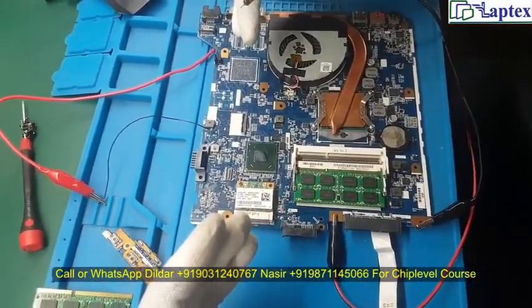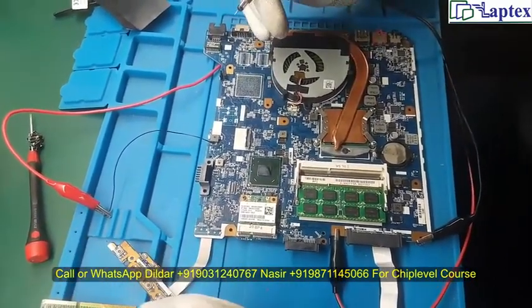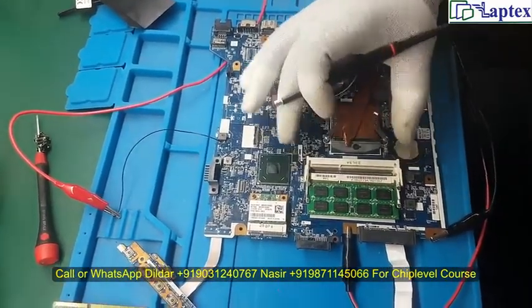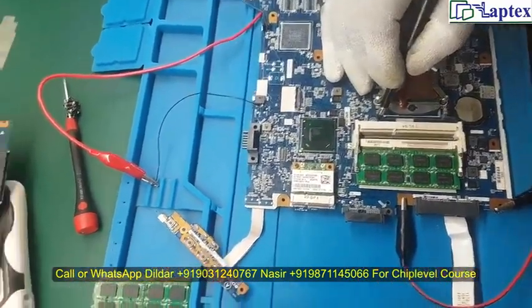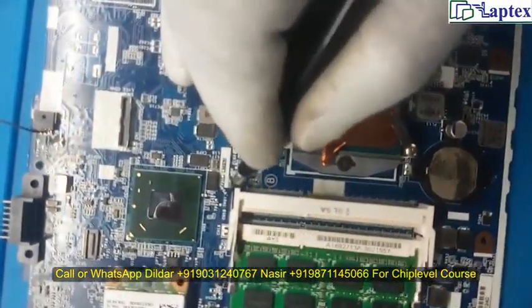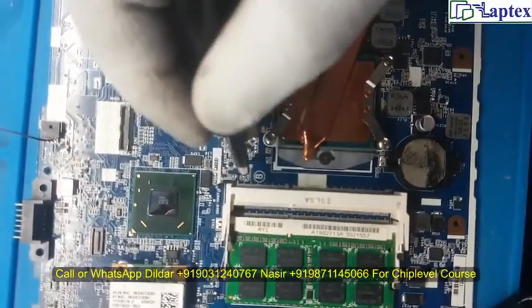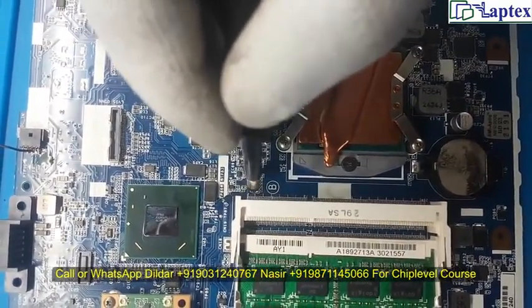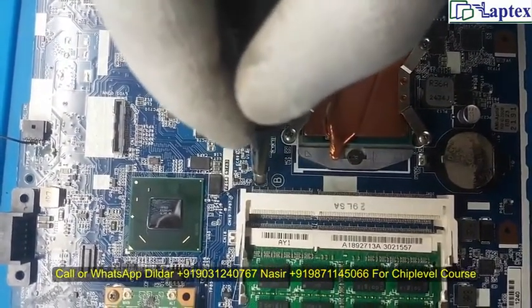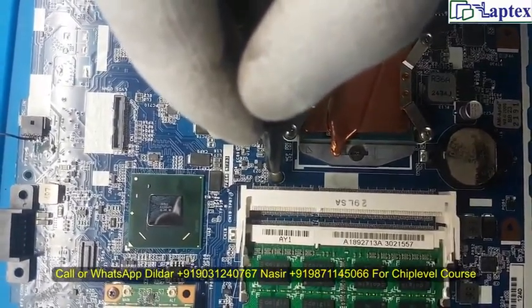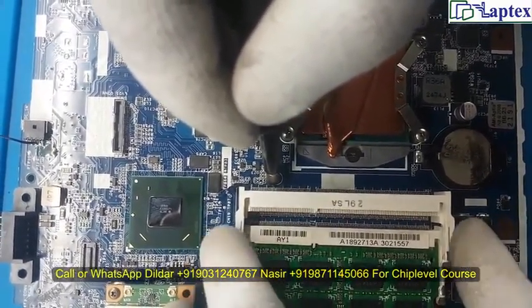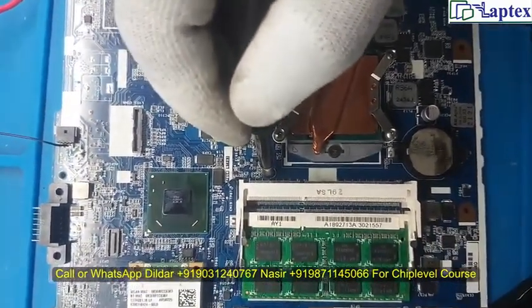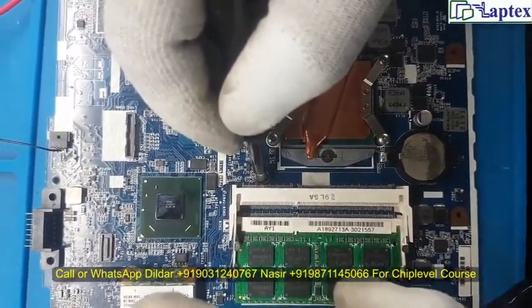Two things you need to remember here, even if you don't have the schematic. If you have a DDR3 slot in your motherboard, it is pin number 30. From here you can see it is counted this way: 1, 2, 3. It is written here also, odd and even numbers, 5, 10, 20, 30. Pin 30 in DDR3, whether it is low or high, 1.5 volt or 1.35 volt, the same point is checked every time for the DRAM reset.